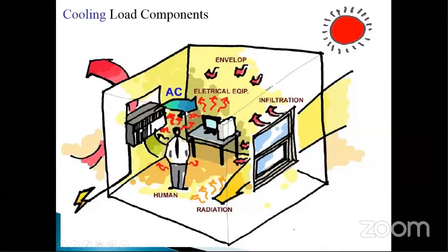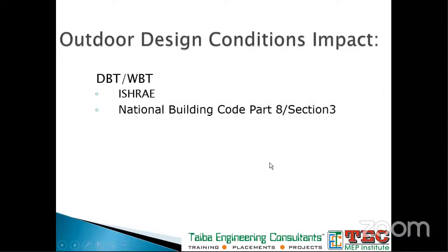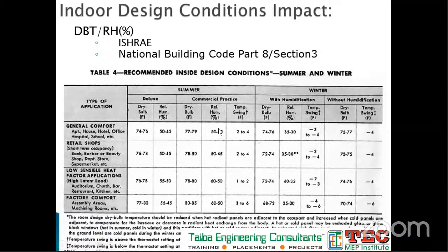There is also an impact of outdoor design conditions on our cooling load. So that's the reason we are supposed to select the right weather file. For Indian cities, we may get the details from ISHRAE. And then we have to set a proper indoor temperature, because if you set your thermostat to too cool a position, again the overall power consumption will be higher.